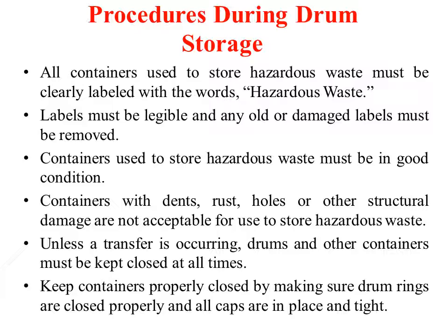Next, the containers used to store hazardous material should be in good condition. That means the container should not have any dents, holes, rust, or structural damage. It should be proper, in good condition. Next, unless transfer is occurring, drums and other containers must be kept closed at all times. Next point, keep containers properly closed by making sure drum rings are closed properly and all caps are in place and tightened.